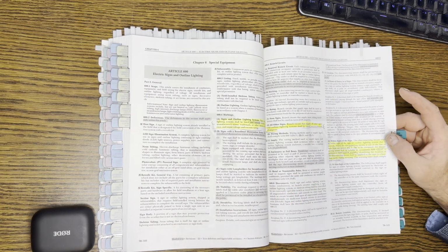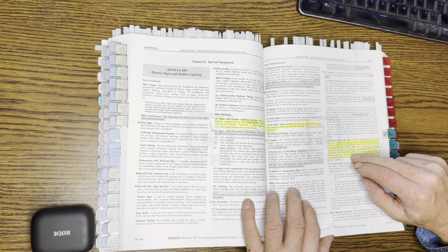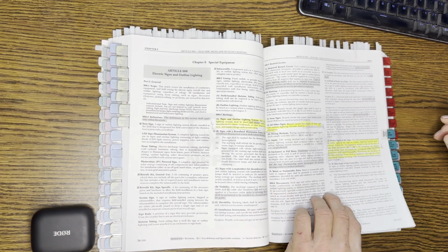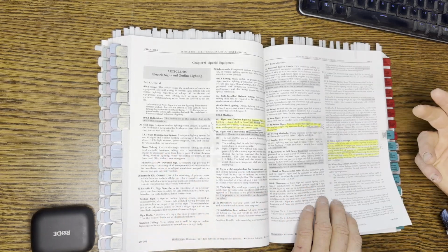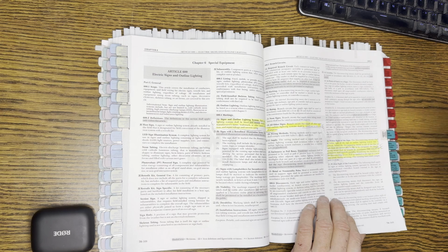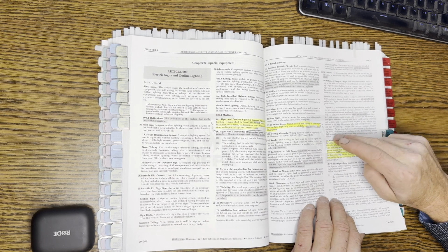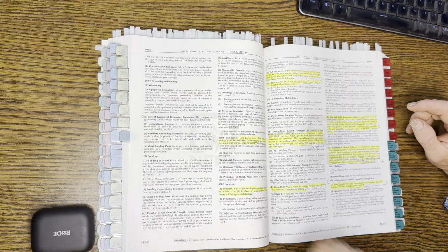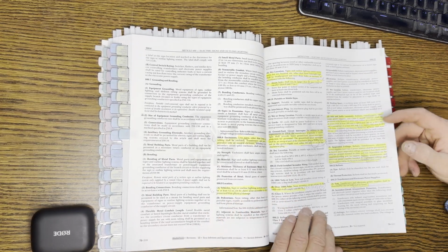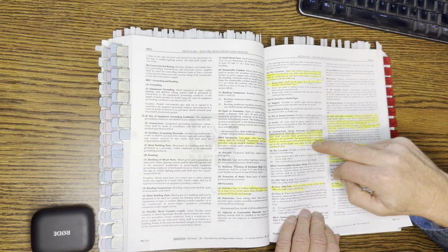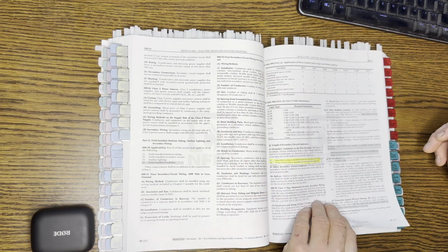So just keep in mind that there are some definitions here, and it would be important for you to know that, because it came up in a couple places that I've seen. In other words, you have to have ready access or accessible power switches, but it has to be within line of sight, and that means 50 feet away as well as line of sight. You can't go over 50 feet. I think it's 50. It's been a little while since I looked it up, but what I'm telling you is look it up in your definitions, and it'll help you.